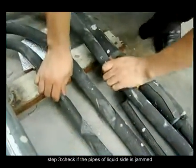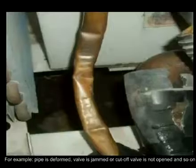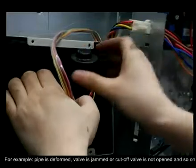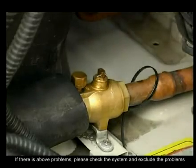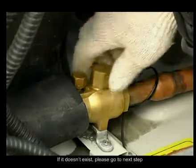Step 3. Check if the pipes of the liquid side are jammed. For example, a pipe is deformed, a valve is jammed, or a cutoff valve is not opened, and so on. If there are the above problems, please check the system and exclude the problems. If it doesn't exist, please go to the next step.